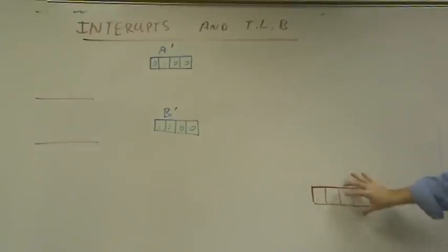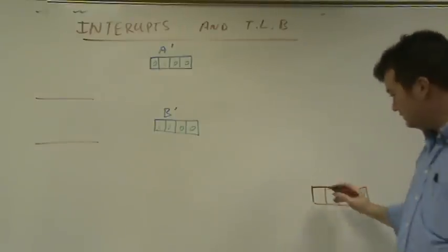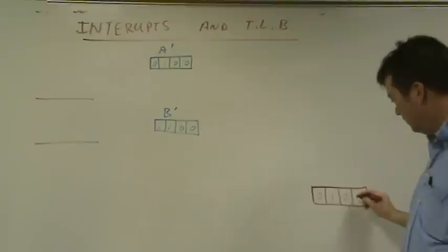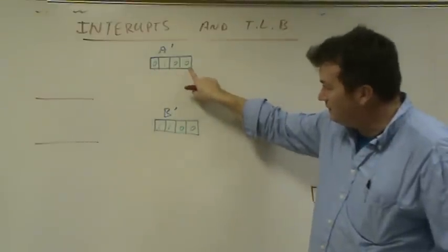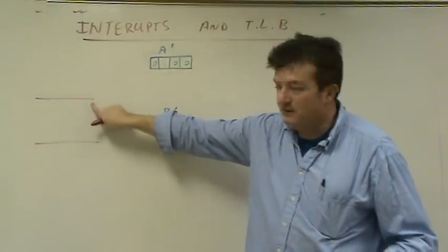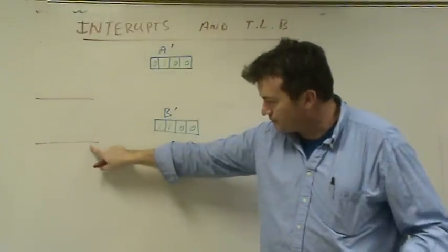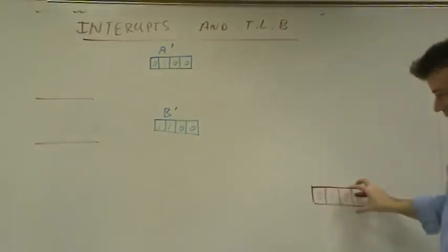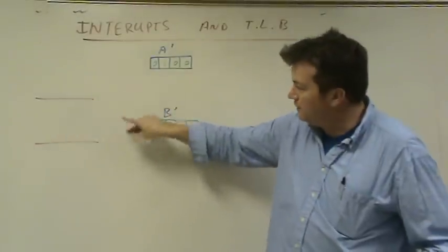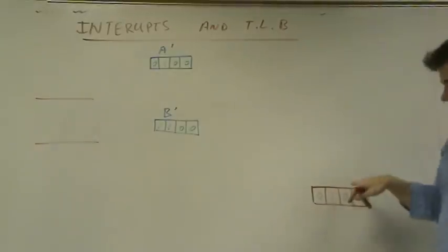This is going to be like our output. We would like this to be 0, 1, 0, 0. If that's what the contents of this is and this line is turned on, then I want this to be copied here. If this line is on, then I want this content to be copied here. So the line that's on will determine which register gets copied over to here.